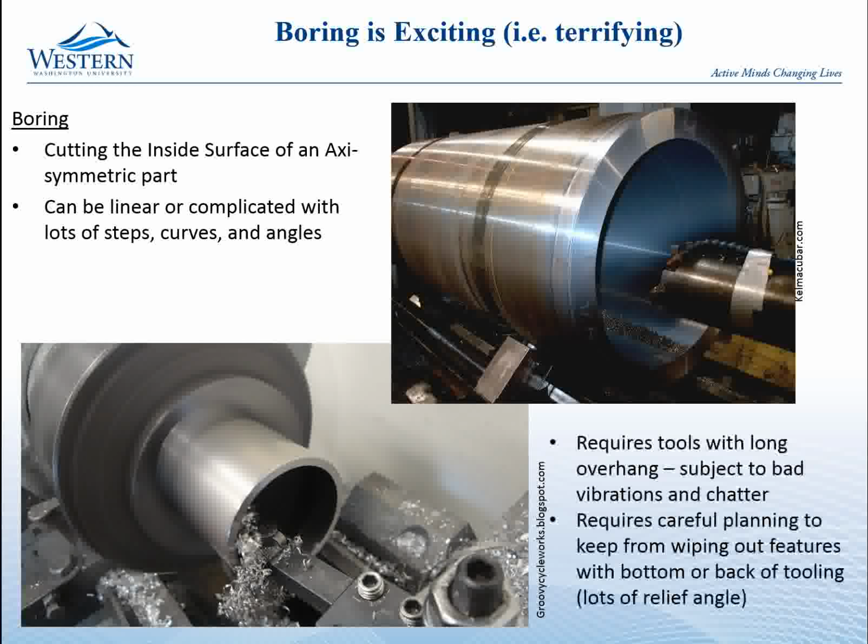So it requires tools that have a very long overhang. So you can see this boring bar has to be able to stick all the way up inside the part. And so it has to be pretty long because the tool has to be mounted way back out here. They often have bad chatter and vibrations because the boring bar is so long. And so look at the size of this thing. This is a little tiny tool out here, and this thing looks like it's 8 or 10 inches in diameter to support that little tiny tool, and that's just to try to deal with vibrations and chatter and deflection that might be in there.